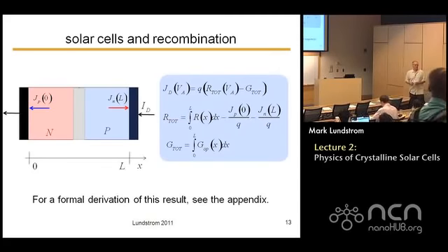And I'm just going to state it because it's kind of obvious. And I have it in the handout notes. I have a mathematical derivation of this, but you really don't need any mathematical derivation. All you need are these little pictures of electrons flowing around in the external circuit. So the diode current, J sub D, is equal to, I argued that any time an electron and hole recombine in the semiconductor, 1 electron flows in the external circuit. Okay? Any time an electron-hole pair is generated, if I collect it, it flows.